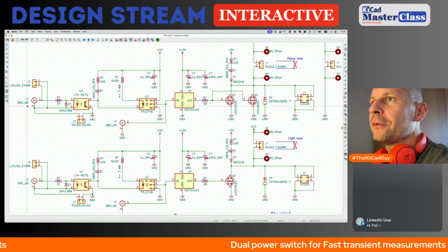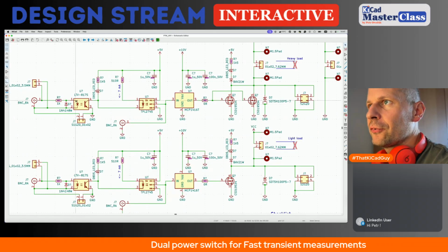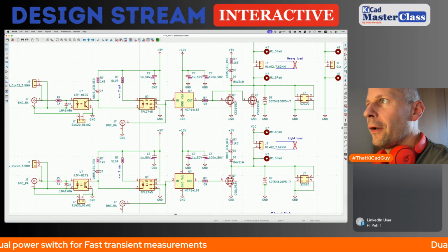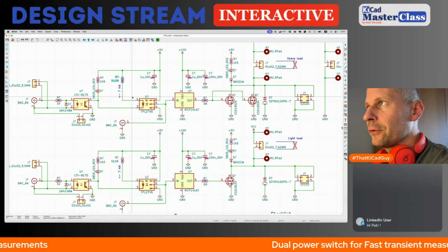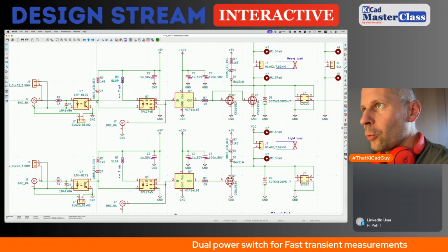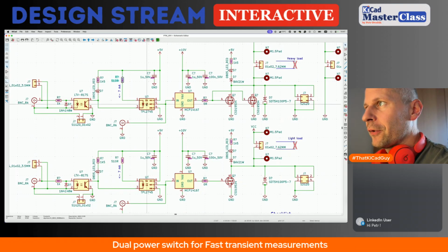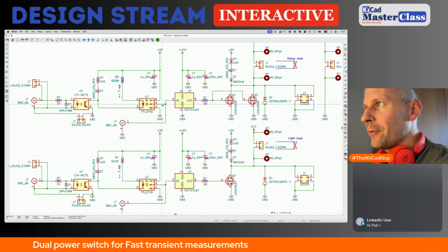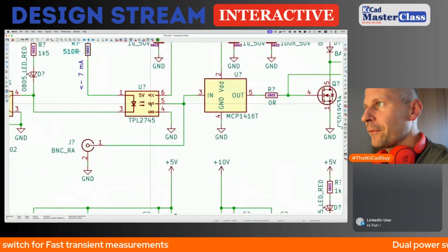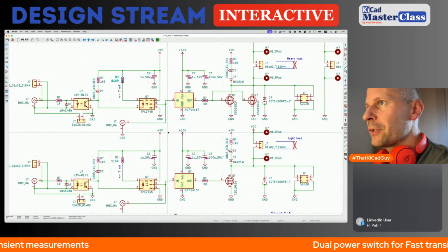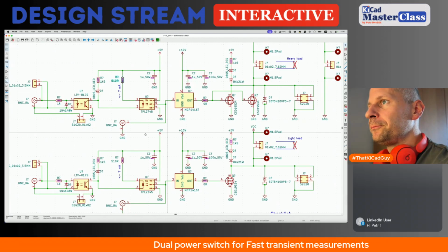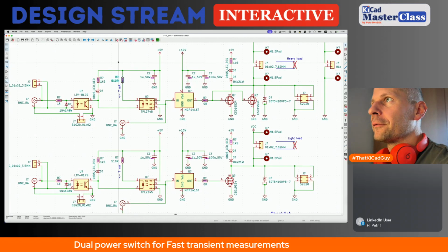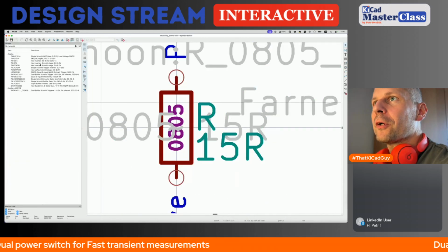When the output is active, high, this will be low, and the LED is supplied from the 5 volt, so low level will cause the activity, and output is direct, not negated, so there is no polarity inversion. So we need either buffer or inverter.